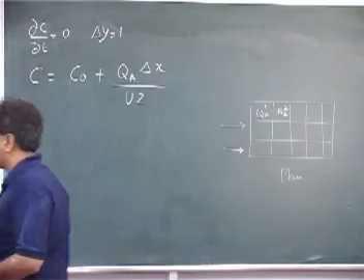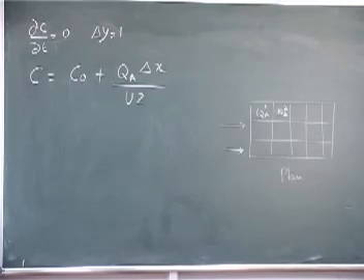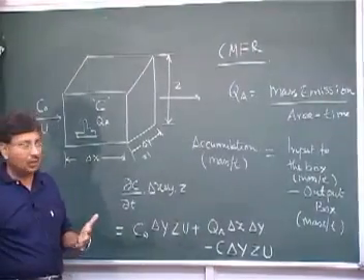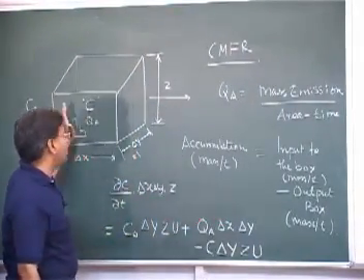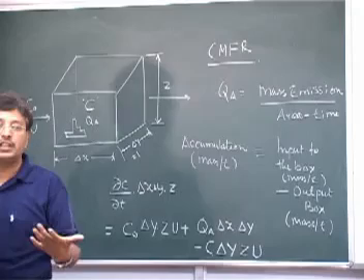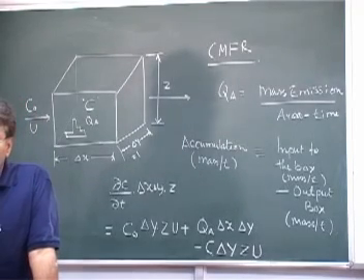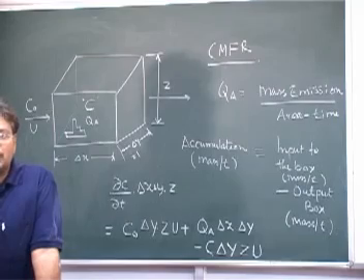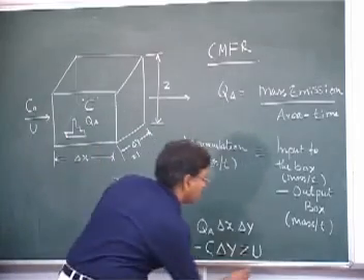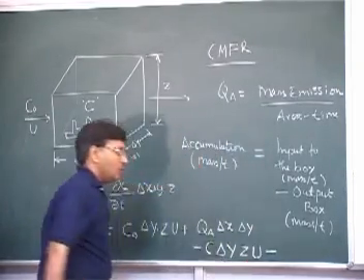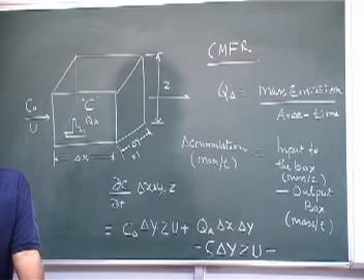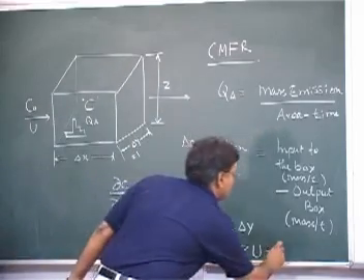Before we make some example and things like that, suppose the same pollutant was decaying in the box. Okay. It means the output is not only because of the wind that is cleaning the box, but there is a decay, and the rate constant for decay is, let's say, K. Okay. You have done that before. That is a decay rate constant for that pollutant, whatever that pollutant is. So it means concentration will decrease. Okay. What do I write if decay constant is K? Kc. All right. Kc.